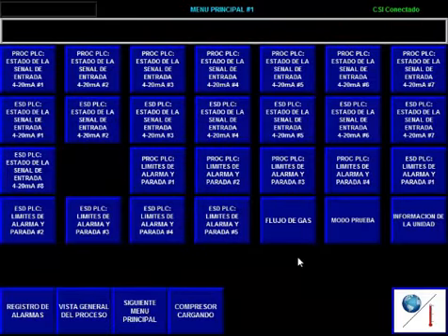Now we'll have a look at rod loading. You can see high alarm and high trip for rod loading cylinder 1. This is a double acting cylinder. These pages don't need to be referred to after initial setup. Everything's set, and the only need to come to these pages is to have a look at the alarm set points.